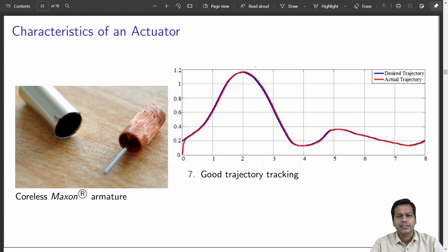Good trajectory tracking. Most of the jobs that a typical industrial robot does are point to point in nature, like a pick and place task, spot welding, etc. And having a slight deviation from the planned trajectory can be taken care of easily while programming. However, jobs like arc welding, painting may require a very good end effector trajectory tracking capability. These end effector tool trajectory demands call for a good joint trajectory tracking capability for its actuators.